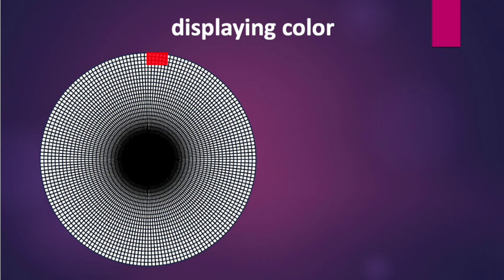In terms of circuitry, however, this color mixing is quite problematic as the LEDs can only be switched on or off. This is why most color LEDs use pulse width modulation. This means that the LEDs are switched on and off at a frequency that is invisible to the eye. The brightness can be adjusted via the ratio between the switch on and the switch off time, the so-called duty cycle.